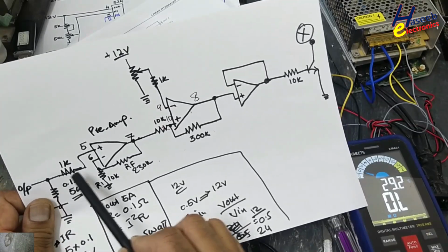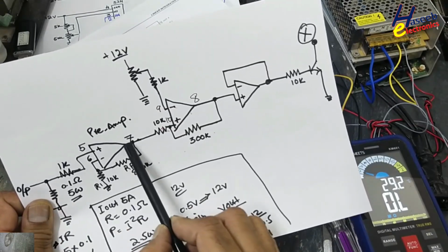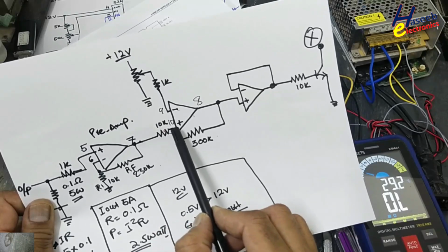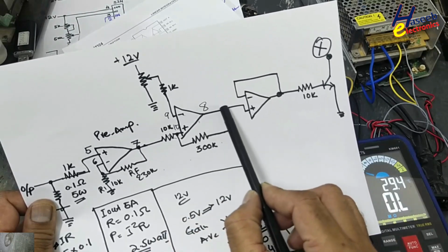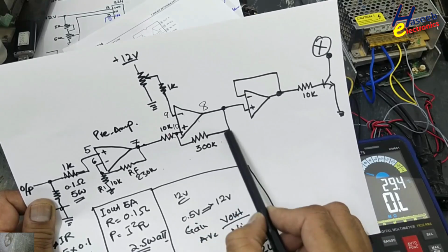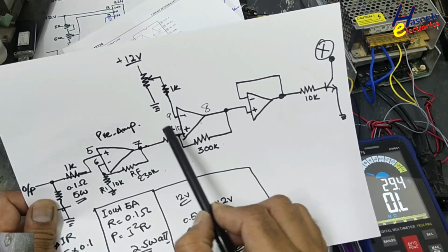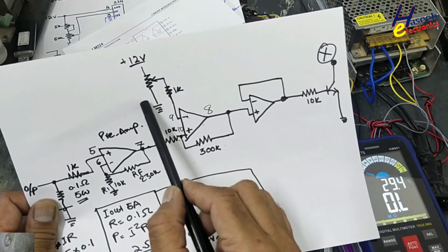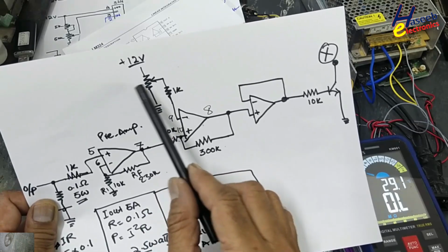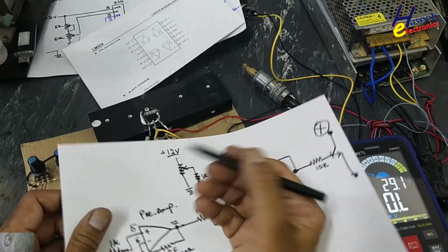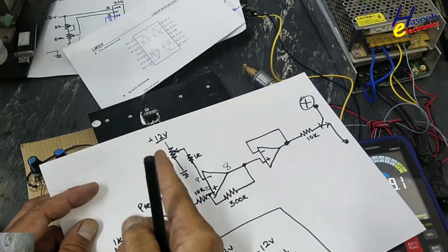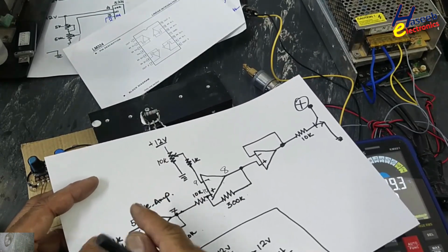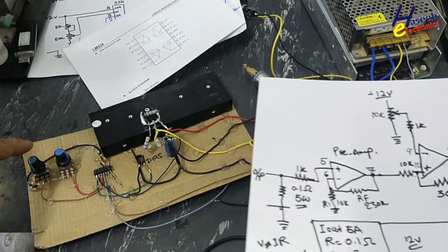The signal is injected to this preamplifier, and the output of this preamplifier is injected to the differential amplifier using a 10k resistor. Feedback 300k. And now we need a comparable signal from a 10k potentiometer. 10k, 20k, 50k. It is the best option to use a multi-turn potentiometer here, or we can connect the same coarse and fine adjustments for current as well.